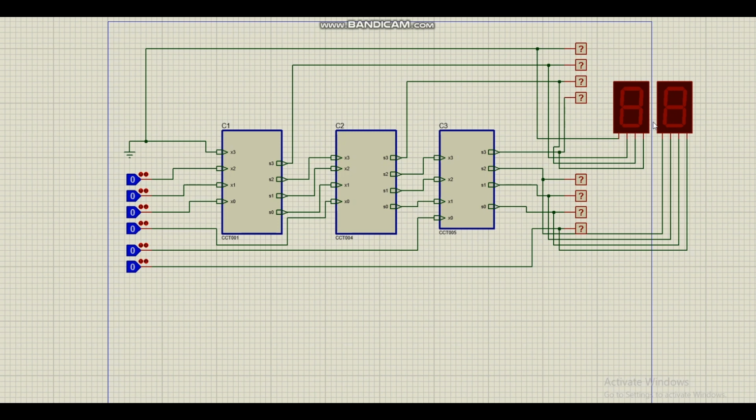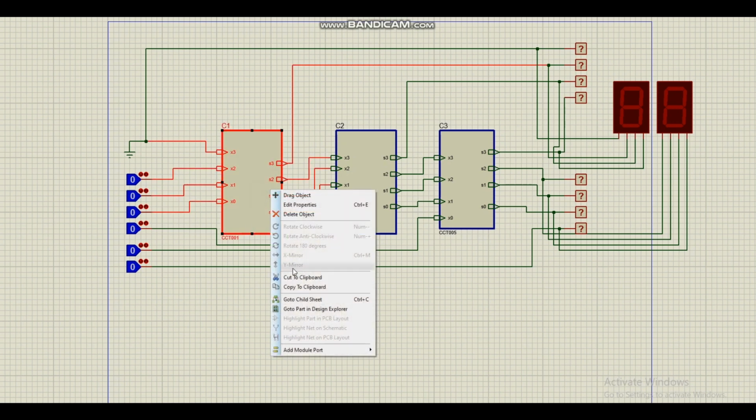the value of 5. If it is less than 5, we keep doing our shifting, but when it is greater than or equal to 5, then we add 6 to the number. We did that by constructing a truth table and plotting the corresponding Karnaugh map.